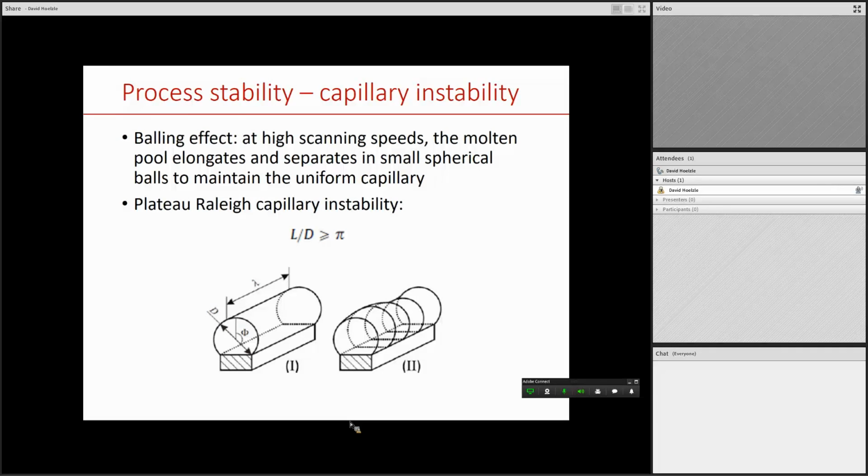Where I've seen it is in powder reuse studies, where they intentionally changed the pressure because they were worried about oxidation of the unused powder. So that might depend on the nature of the powder too, right? Because different metals can oxidize. Yeah, they oxidize at different rates. Definitely, due to the rate of oxidation, we definitely have it.